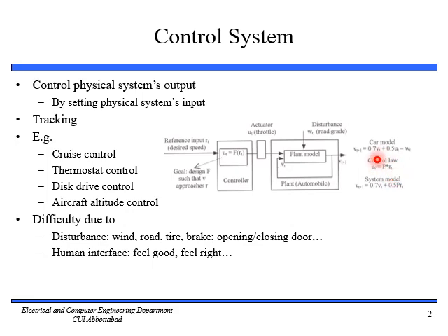This is just proportional, some fixed value, like a multiplier. So our system model will become the same: v of t plus 1 equals 0.7 v of t plus, now we have to replace u of t with p into r t, so 0.5 p r t. We have ignored this disturbance because this is not a part of the car model, it's just an external disturbance. We can also include it here, so it will become minus w t.